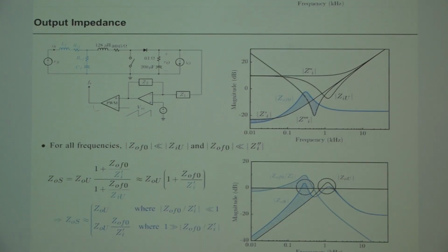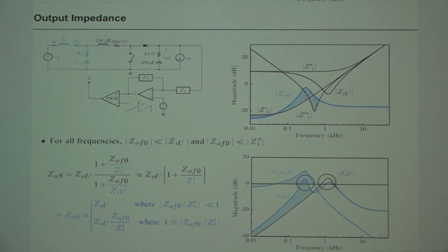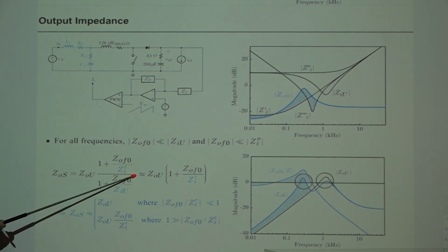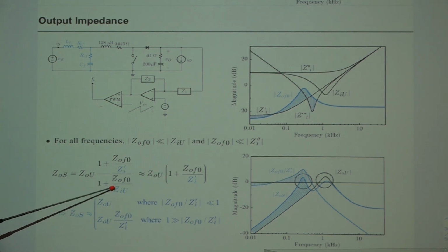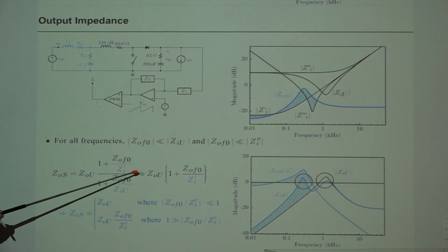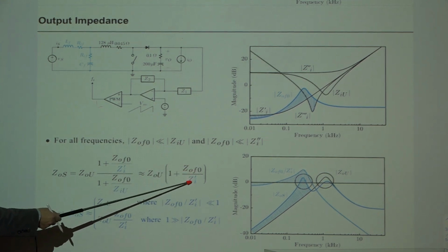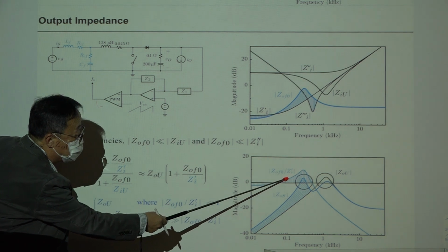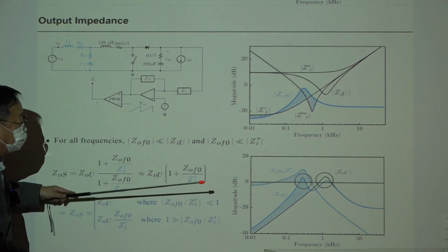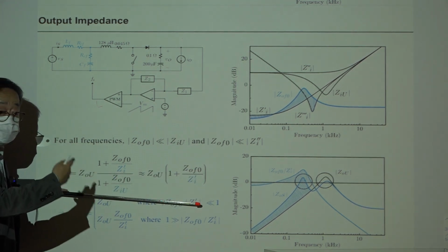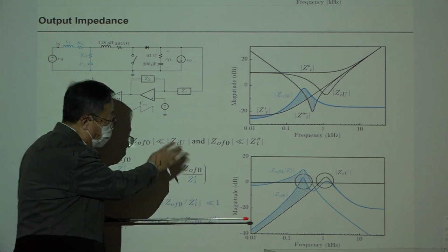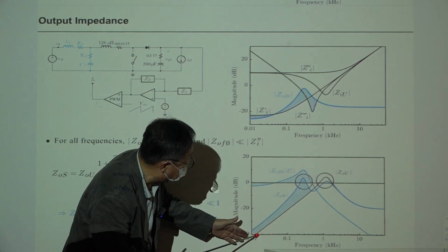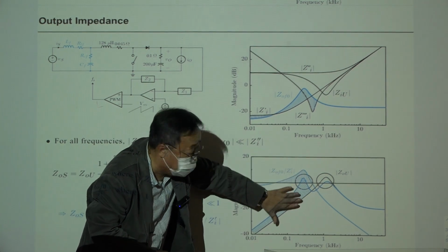Then next, this one is output impedance. This is the expression for the output impedance. This one is again what? This is the closed loop input impedance. So this becomes 0, considered to be 0. Then the remaining is this. Then this ratio, GOF divided by GI prime, which is basically the overlap, is this one. But it appears in the numerator, upstairs. So the output impedance of this uncoupled converter is boosted this much at this frequency.